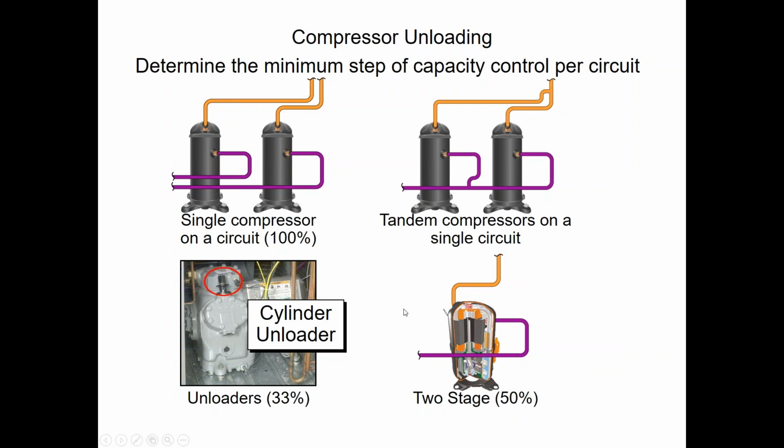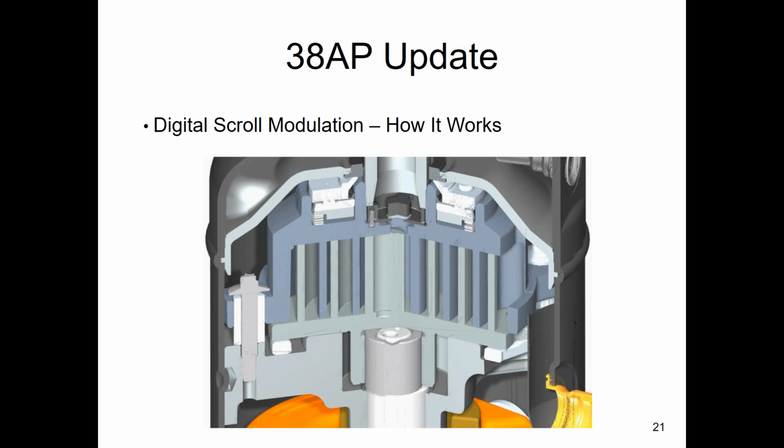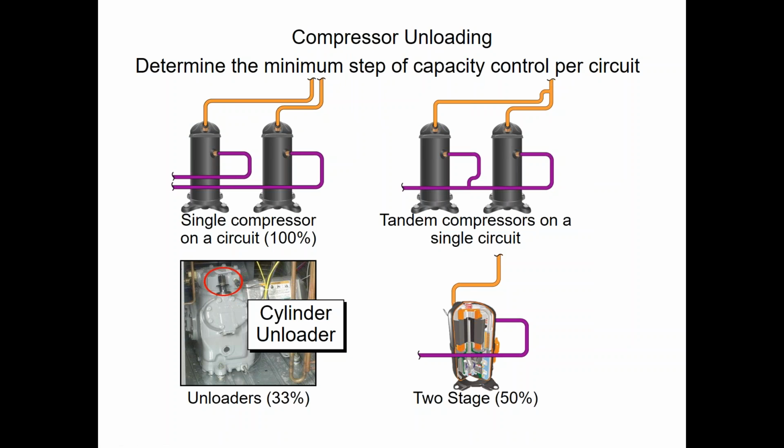Got it. Some of our rooftops, we have 2 unequal sized compressors. Do we have that happening in any condensing units? Oh yeah, a lot of them. So we have like a 4-ton and a 6-ton in the condensing unit in order to get 3 stages with 2 compressors. Usually in our condensing units, when you're talking that small as tonnage, you're in the 38AUZ, AUD product line. And most of the time, those are equal tonnage, equal split.